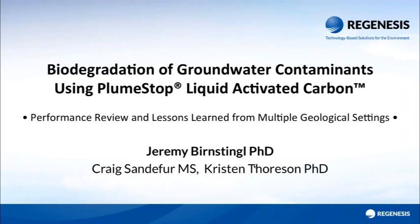The first point is that the PlumeStop will only be mobile for a period of time. The treatment that secures the movement of the material will last for about 1 to 3 months, depending on the setting. After that, all of the material will be just locked in place. Ahead of that time, the material will leave a coating really from day one, and that coating will not wash out. We've done tests in the lab which show this, but to me, the most convincing indication of just how well PlumeStop will stick to a formation from day 0 is from when the material has actually surfaced during application.